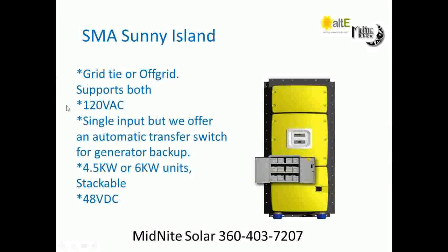Some UPSs, like smaller UPSs you buy for your computer, actually run the computer off their output inverter all the time from the battery, and they have a separate battery charger in the box charging the battery. So there's no pass-through, but from an efficiency standpoint, that would be horribly inefficient for a whole house. So it's an actual transfer, but it's done in about 2 or 3 cycles, probably about 1/100th of a second.